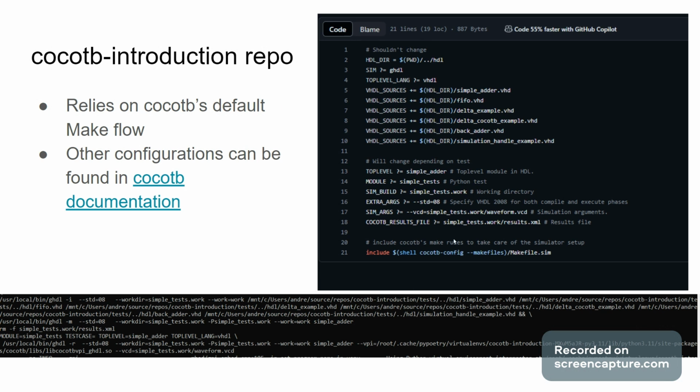I'm not going to get too much into this. In fact, I'm going to recommend that you don't follow the same flow that I did. cocotb supports a makefile system if you just want to get tests up and running, but I just found out recently that apparently there's a much better way using PyTest and I think a Python runner to run tests. This is an older approach using a makefile system, which is part of the reason I needed Linux, so I had access to Make. But I don't think you need to use the same approach anymore.